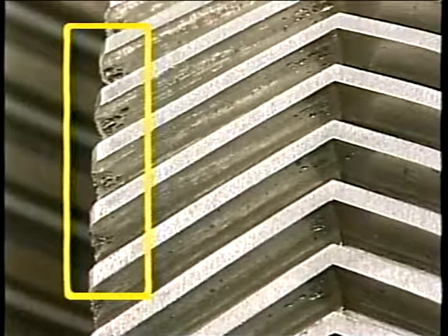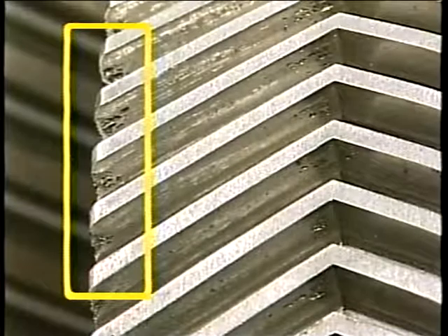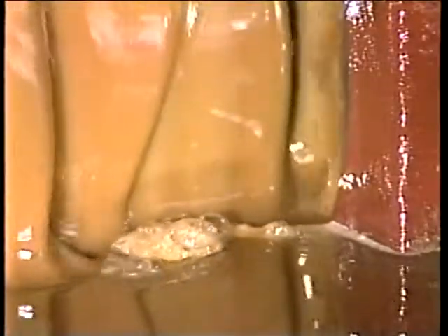Contaminated lubricants may cause a rapid erosion of gear teeth, which can cause teeth to break. The contaminant may also cause foaming of the lubricant, which can reduce the flow of lubricant to parts of the gear set, and this condition can reduce heat removal. You can prevent contamination from causing excess wear by replacing the lubricant at regular intervals.